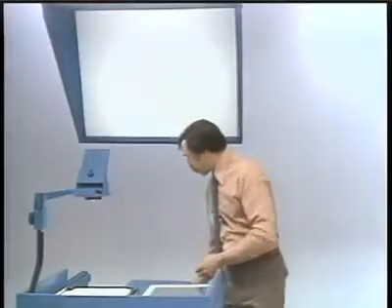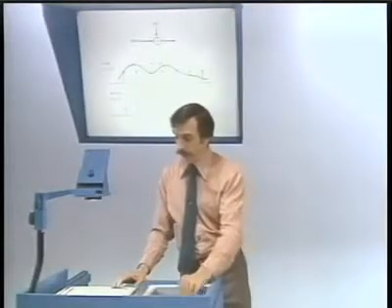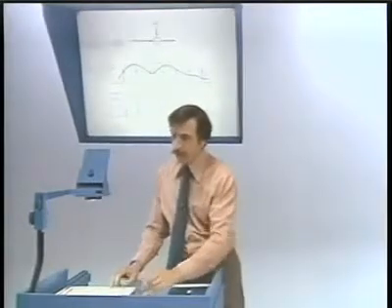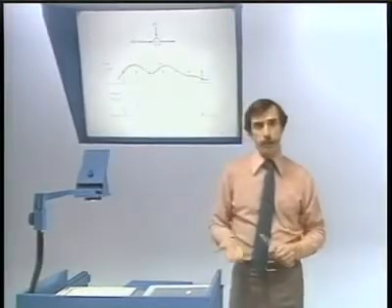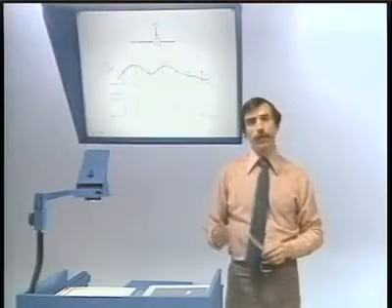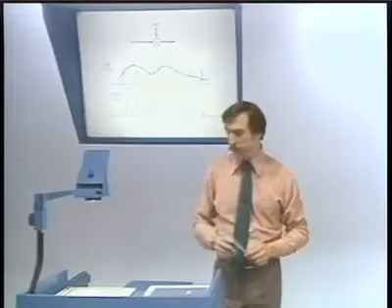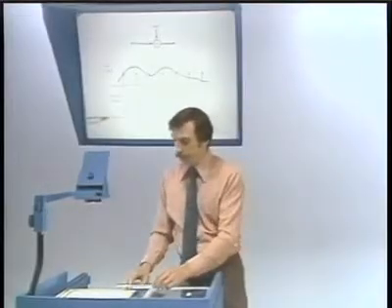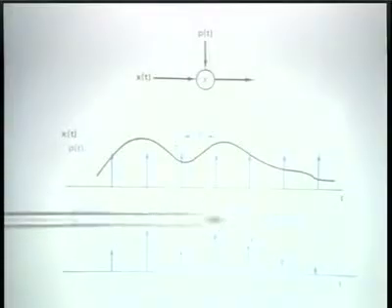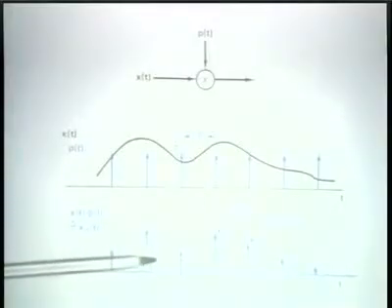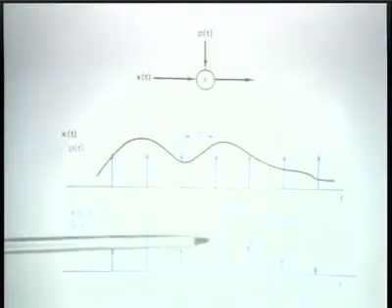Now let me stress, going back to the picture in which we had done this modulation, that this process where the carrier signal involves an impulse train is often referred to as sampling. And what that means specifically is that this resulting impulse train is in fact a sequence of samples of the original continuous time signal.